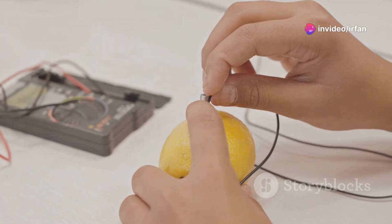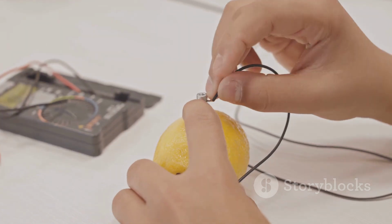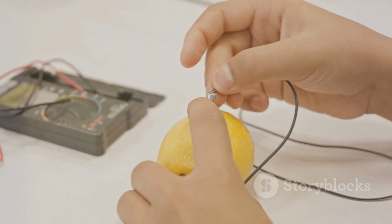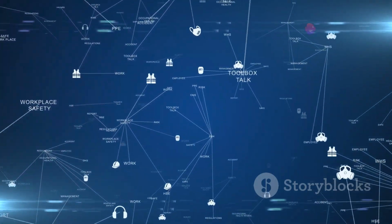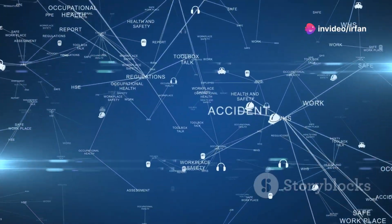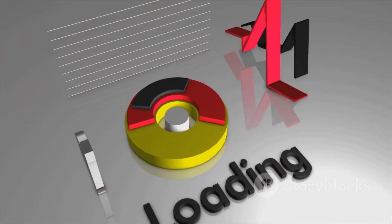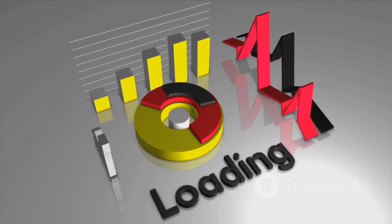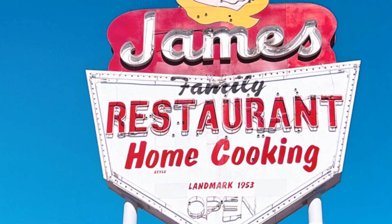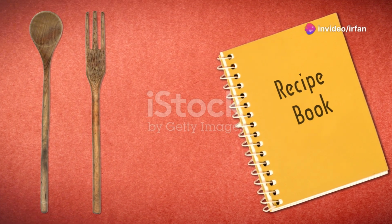You create connections by dragging wires from the output port of one node to the input port of another, establishing a directional relationship. A graph is the visual representation of your Dynamo script, comprising interconnected nodes and connections. It visually depicts the sequence of operations and the flow of data within your script. Think of nodes as ingredients, connections as recipes, and the graph as your culinary masterpiece.